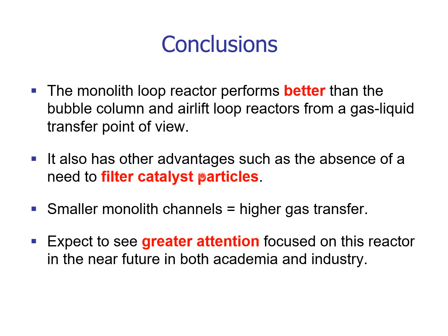It also has other advantages in relation to bubble column slurry reactors, because there is no need to filter the catalyst particles, because the catalyst is introduced as a thin layer coated on the inner surface of the single channel within the monolith construction.